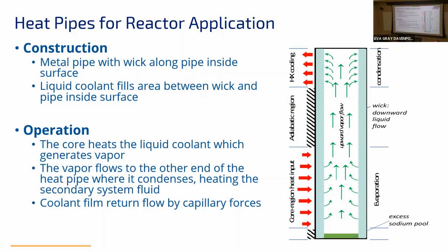We assume, based on more detailed analyses, that when you are in the right operating limits for a heat pipe, it is heat piping, shall we say. It is removing heat. You have sufficient capillary flow. When you get into an accident situation that pushes you beyond those operating limits, we then break down and reduce to a mass and energy balance effectively. And it's overall simple.